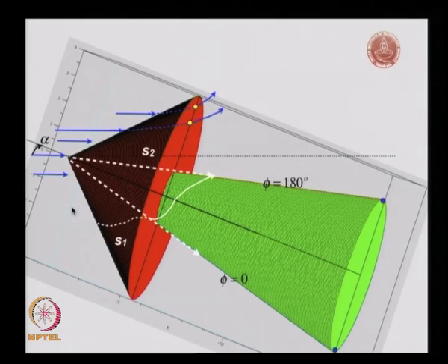So you have this cone, the flow comes in, enters the shock, reaches the bottom of the cone surface, and then curls around and goes up to the top, and all these streamlines are curved. If you look at this, I have drawn this streamline here, part of which is dotted, another is solid. This dotted part of the curve is going inside the shock wave, and then it goes from the bottom of the cone and curls around and goes to the top, and then it tries to merge over here at this particular radial line.